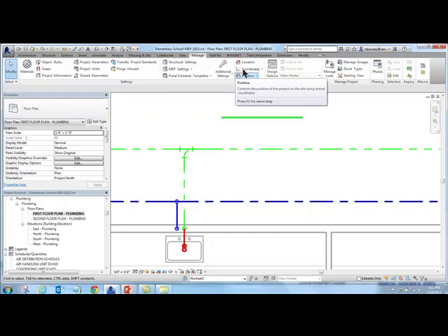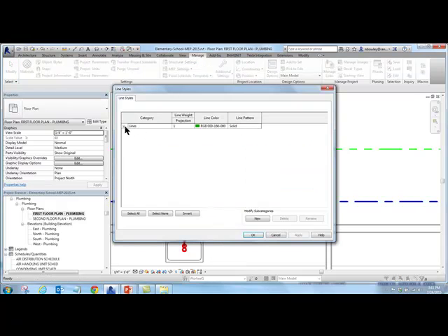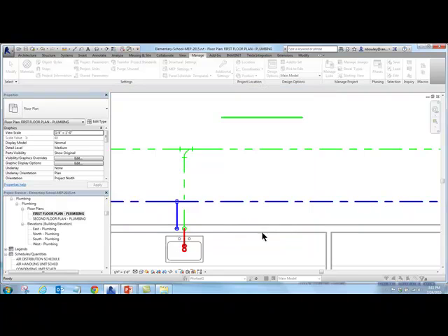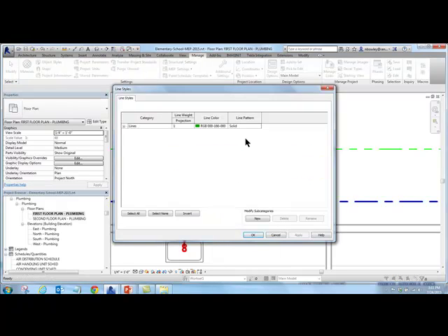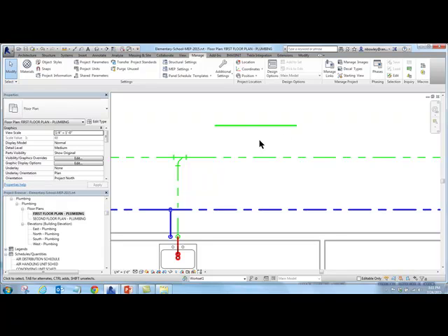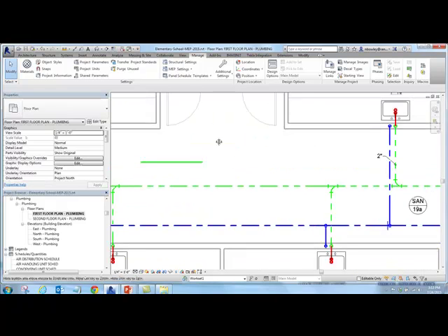All right, so let's change that back. But that was just the beyond line style I changed there. So that was under Manage, Line Styles, find Beyond, and we'll set it to a normal dash. And now it's fixed. Oops, I messed something up. Oh, did I? Okay. But that's all it is. I probably spent a couple of days trying to create a filter for things that were in a negative elevation, negative offset from the floor I was working on, and that's all it was.